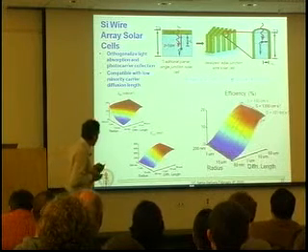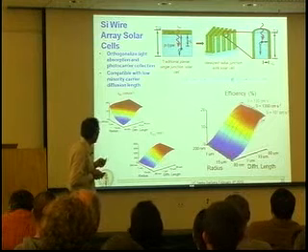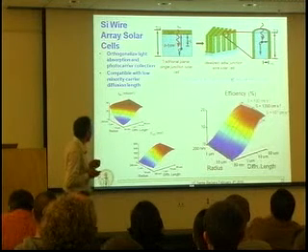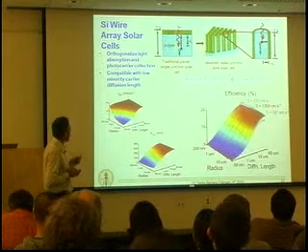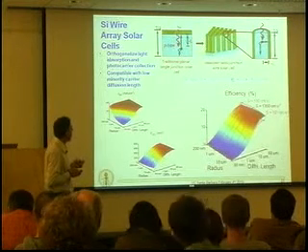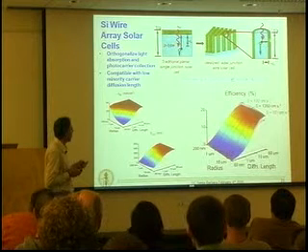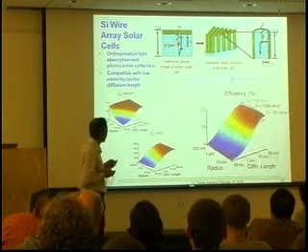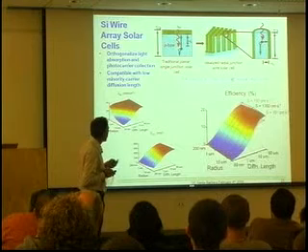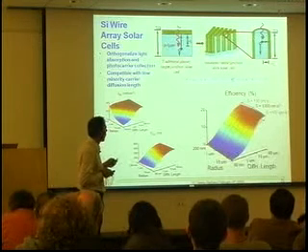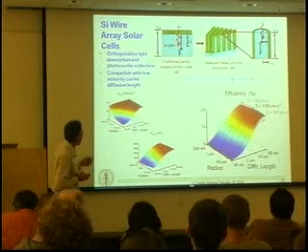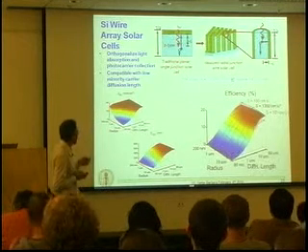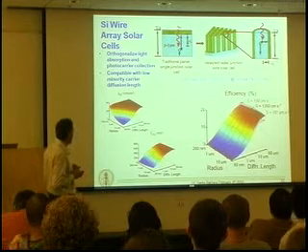So a couple of years ago, we began work on a type of solar cell we call a wire array solar cell. This was initially motivated by the idea that for low quality semiconductors where the carrier collection length was small, we could have much more efficient carrier collection by having a radial p-n junction, where carriers are collected laterally across the wire radius, even though the absorption is throughout the wire length. So we orthogonalize light absorption and carrier collection. That was the original idea.